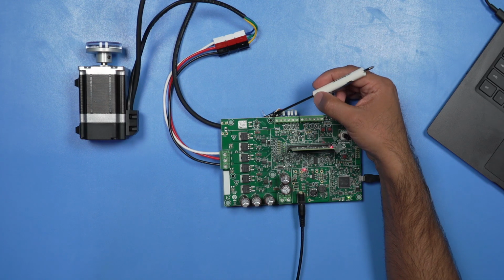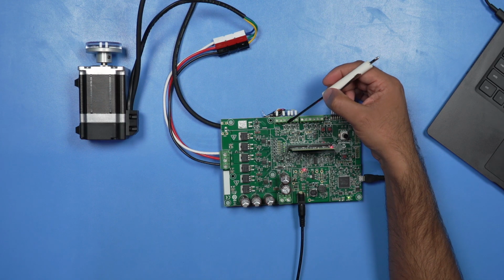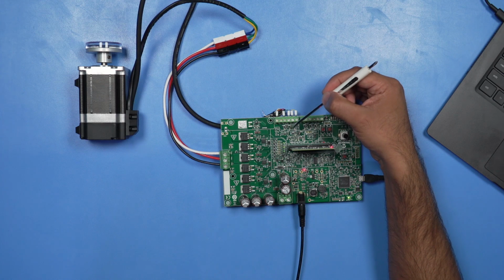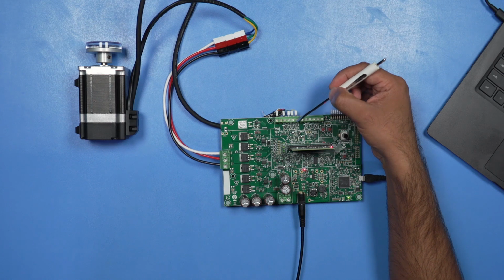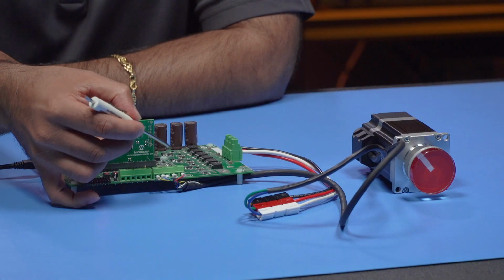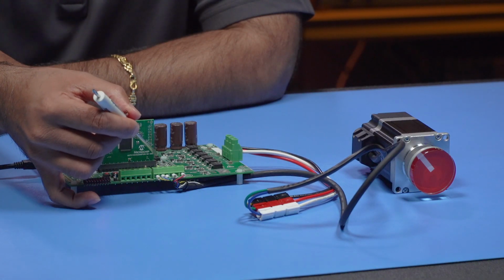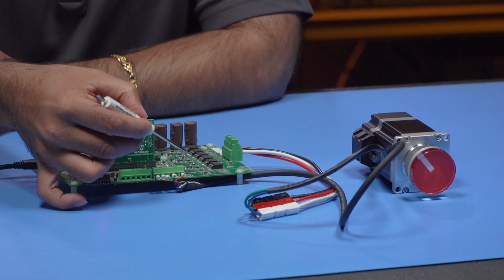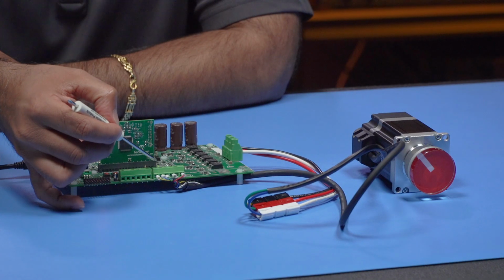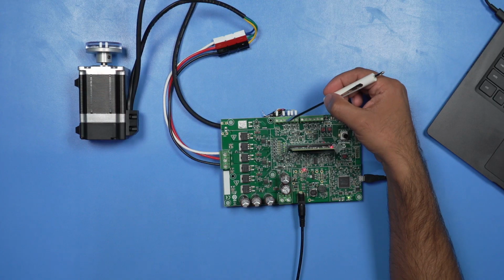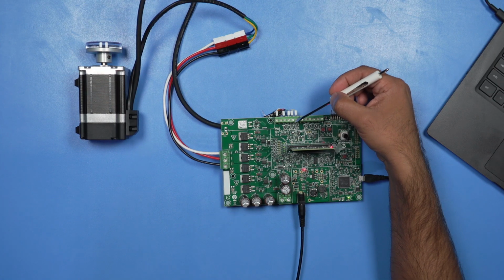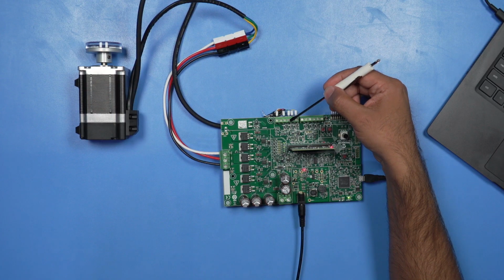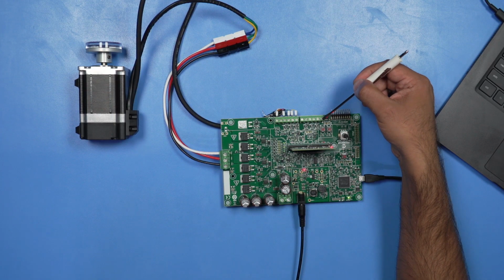So we establish those connections by looking at the data sheet and making sure that they match up with the right pin assignments on this connector. So you can look at the data sheet for the motor. You can also look at the user's guide for the specific development board that you're using in order to match up correctly the wires with their correct inputs here on the connector. In this case, it's an encoder, but if you were using a Hall sensor, you would connect to this particular connector.